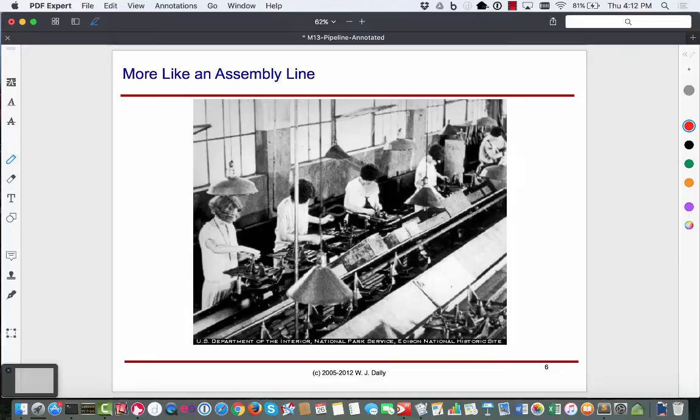So this is where pipelining comes to the rescue. While bit 0 is doing addition of a pair of numbers, the hardware for bit number 1 might be working on the addition for the previous pair, and so on and so forth. So the idea is that I'm not doing the task just once. I'm doing repeated addition. So I have pairs of numbers arriving, and while one stage is working on one pair, another stage is working on a different pair, and so on and so forth.